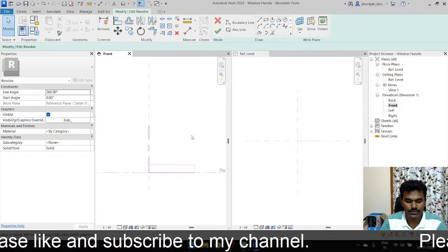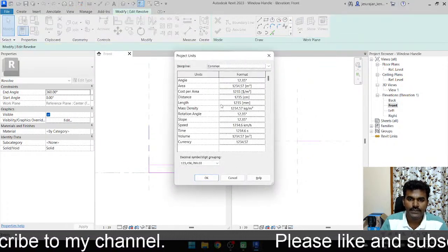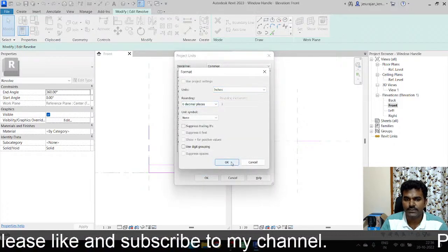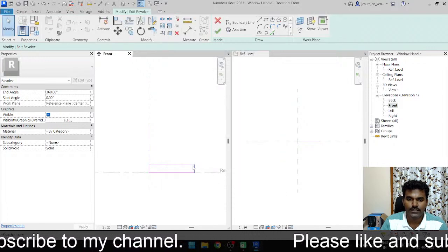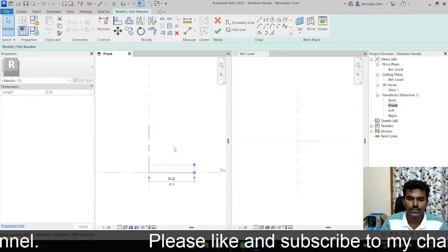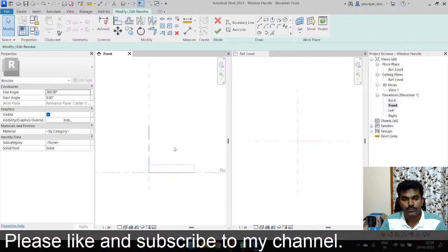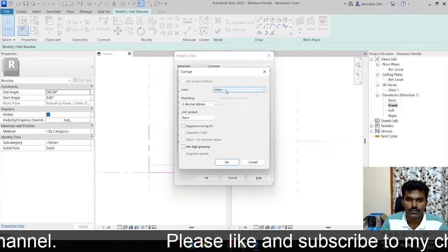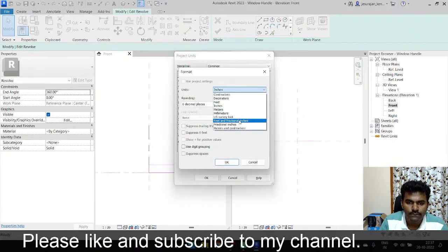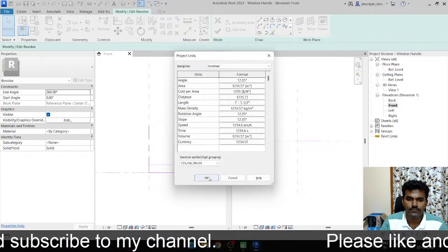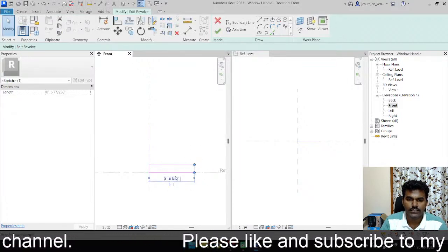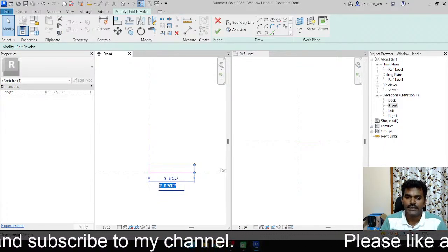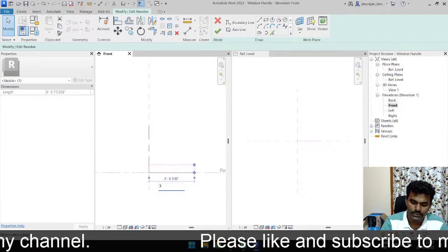Okay, so keep the units as imperial. Go to length, keep that as inches, decimal places 0, fine. Okay, select. Oh, still it is millimeters. Why? Units, length, fractional inches. Okay, select. Door knob, the base is going to be 3 inches.